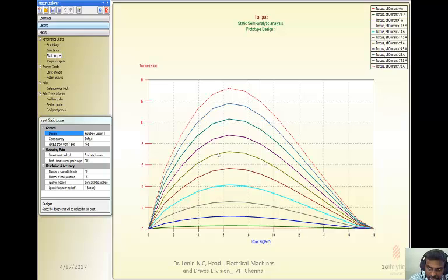But as far as torque is concerned, it is directly proportional to the current. So whatever current we inject here, we can study what the torque, flux linkage and inductance of that machine will be, so that it is easy to understand that whatever the speed of the machine, if we have that particular current, we can get that particular electromagnetic torque.